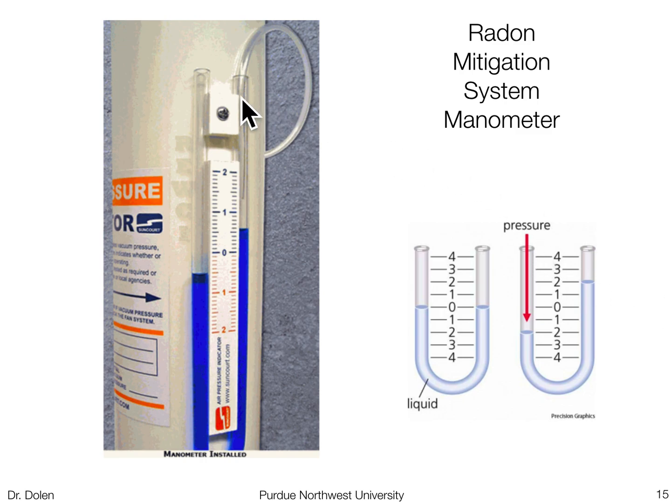All right, so for a radon mitigation system, you may have this radioactive gas coming up from underneath your house. There's uranium in the rocks underneath houses. That uranium decays, a bunch of decays, into radon, another radioactive gas, which comes up under your house. And so you don't want that in your basement. So sometimes houses have radon mitigation systems where basically you want a lower pressure underneath your house so that the radon isn't going to come into your house. In fact, the air in your house, if anything, will get pushed under your house.